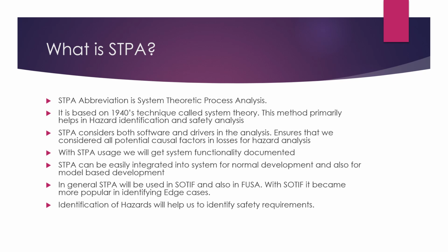STPA can be easily integrated into normal system development and also model based development. In general, STPA will be used in SOTIF and also in functional safety. With SOTIF, it became more popular in identifying edge cases. Identification of hazards with the help of STPA will cover a wide range of safety requirements.